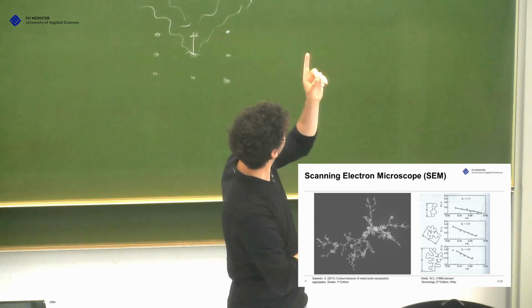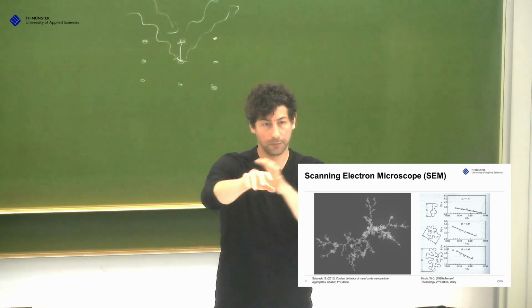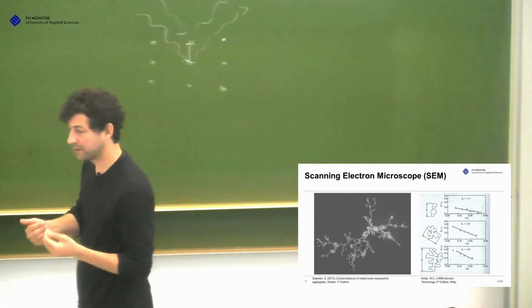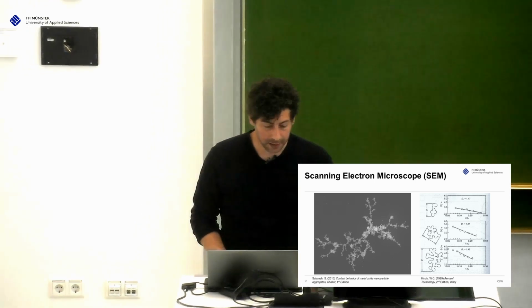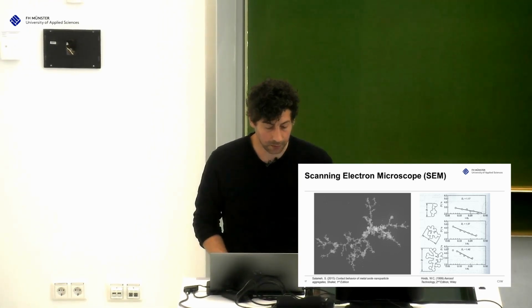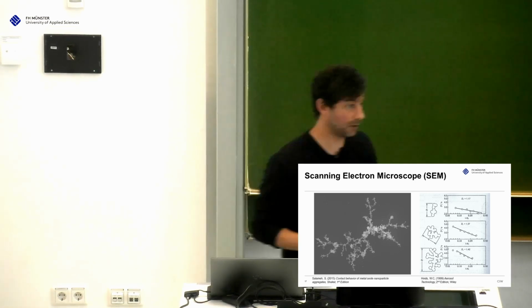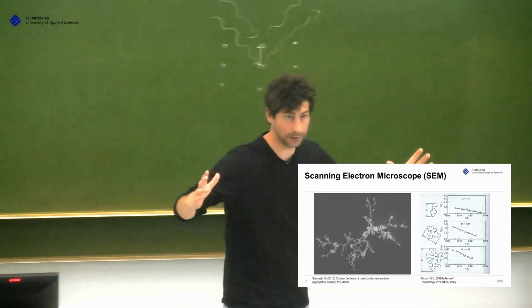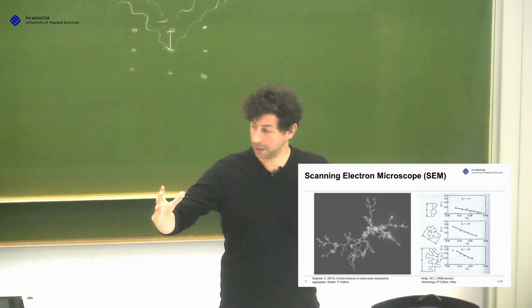And here it's a very open structure with all these arms, and then there are smaller arms and so on. So the fractal dimension is very low. You can determine the fractal dimension from the overall size of the agglomerate related to the number of primary particles and the size of the primary particles, because these will give you the information.